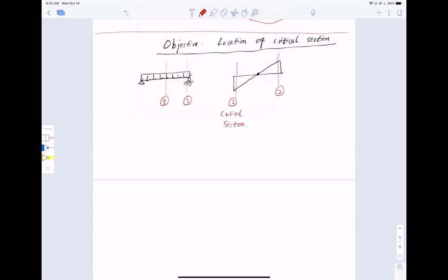Okay, so folks, don't go right away to the middle section. We use the middle section for bending moment, but shear is different. So the answer to the question is we have to design based on the shear diagram, and the critical section at the ends, at the support, is maximum.